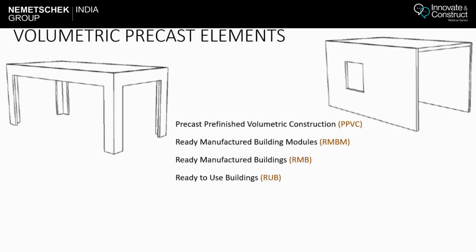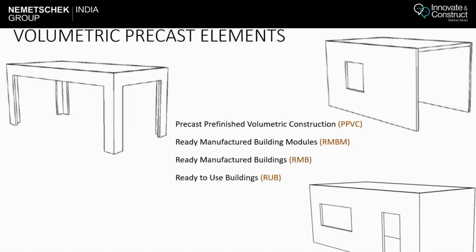Then there is one more type wherein vertical walls and horizontal slab are cast in one go in precast. Then there is the third one, which is again all the walls on four sides plus top slab cast. Again, there are connections with the top element and the bottom element, or other foundation at the bottom or above levels. There are connections as well as side connections.